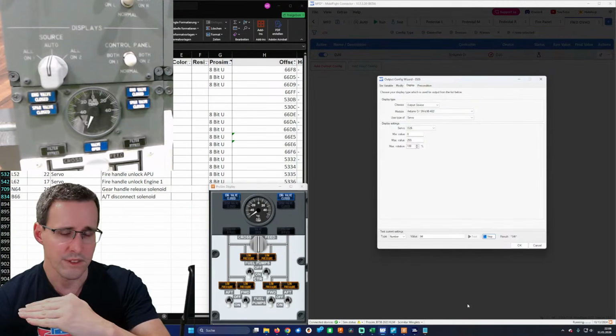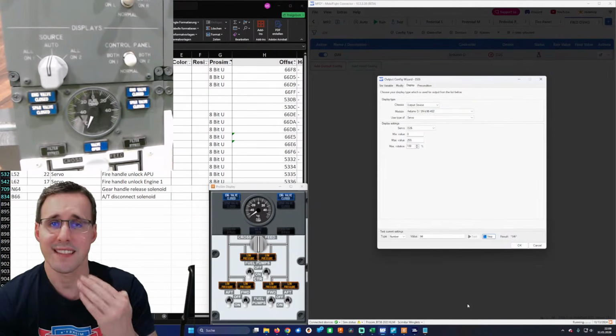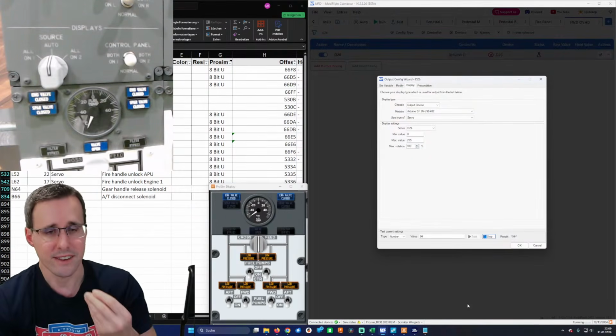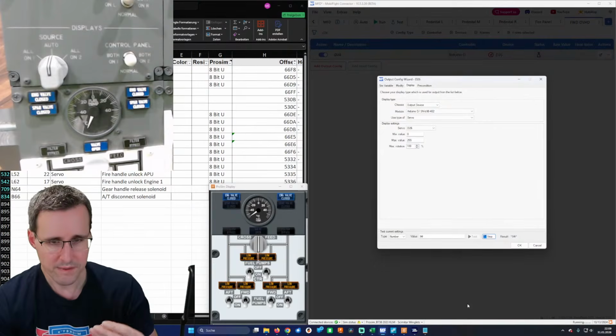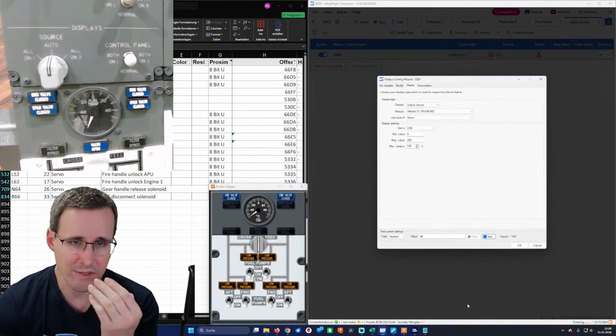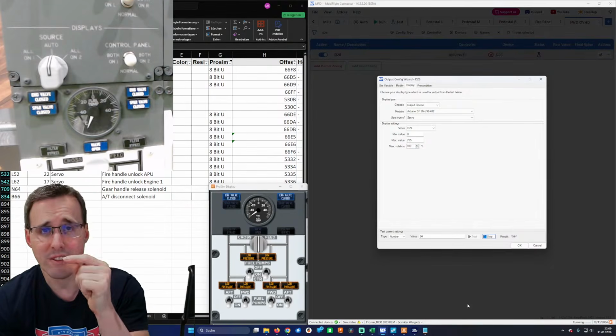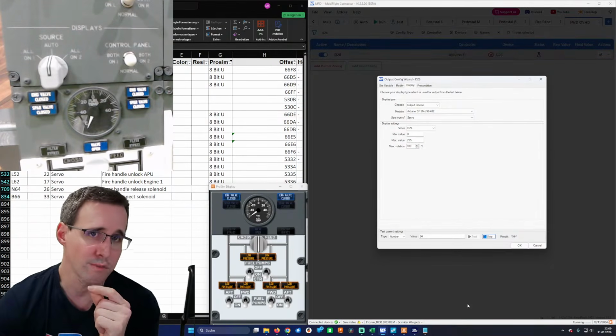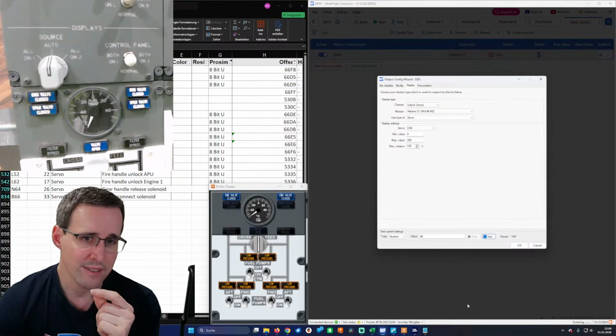You have a zero position. A stepper motor most of the times doesn't have this. You have to add an additional switch that the stepper motor is reaching, so that the system knows, at this position, there's my 0 point. And this makes it a little bit, I think, more complicated to insert stepper motors in your systems.